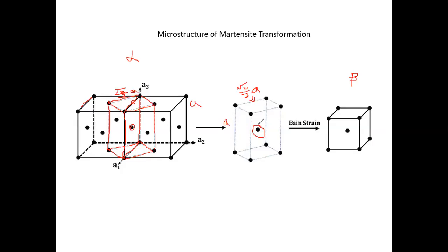It's not on the face anymore, but in the box. Okay, so now this is interesting. Basically, I don't have a cube at this stage, but I have a similar arrangement of BCC. And this is actually taken out from the FCC. So which means that this is an equivalent way of tessellating the whole FCC structure.